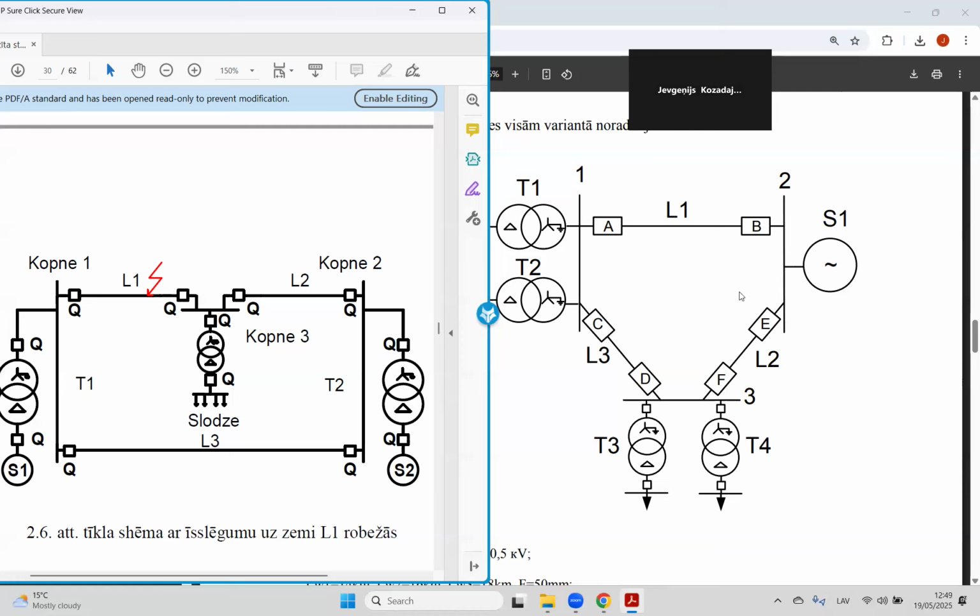That's why for distribution networks, from the protection point of view, we very often try to keep the radial condition, for example by switching off one line, not to have a loop, because for a distribution network the loop is quite complicated.